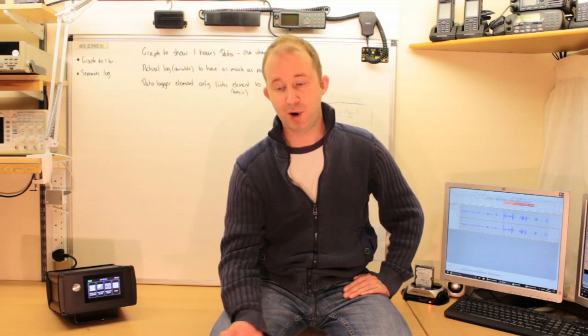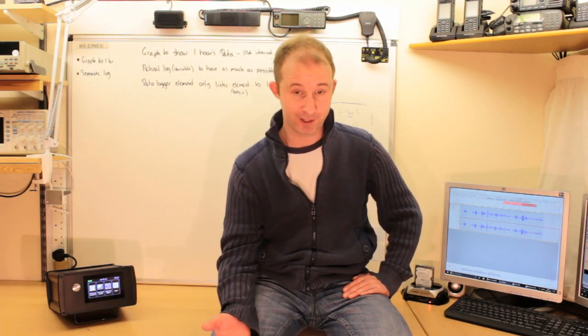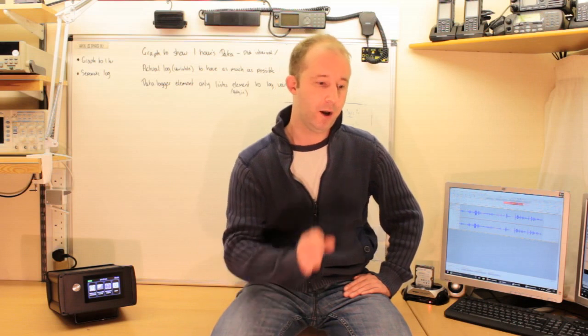And lastly, it will switch on an auxiliary air mover. So if a pressure limit is breached, then one of the things that this device can do is switch on an auxiliary air movement system, so another extractor fan for instance, and that will help to overcome blocked filters or a motor failure on your primary air mover, and it forms a sort of closed loop control system where the system looks after itself.